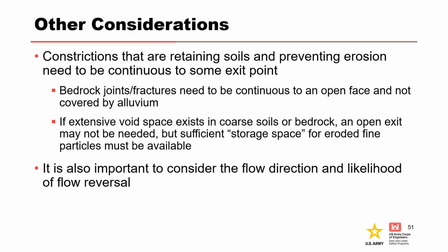Constrictions that are retaining soils and preventing erosion need to be continuous to some exit point. Bedrock joints or fractures need to be continuous to an open face and not covered by alluvium. If extensive void space exists in coarse soils or bedrock, an open exit may not be needed, but sufficient storage space for eroded fine particles must be available. It's also important to consider the flow direction and the likelihood of flow reversal.